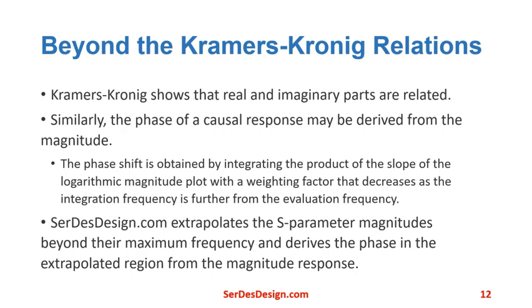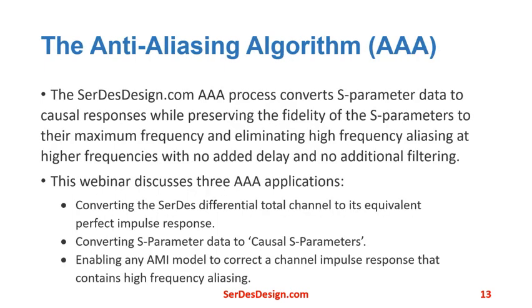The anti-aliasing algorithm. The SerDesDesign.com approach, called the anti-aliasing algorithm, converts S-parameter data to its equivalent causal representation while preserving the fidelity of the S-parameters up to their maximum frequency and eliminating high-frequency aliasing at higher frequencies, with no added delay and no additional filtering.